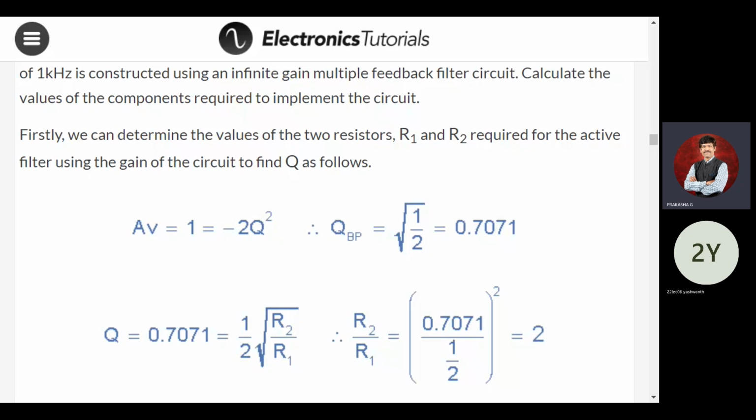One more thing, band rejection is also there. Band rejection, what is it? I'll give the same input signal to the low pass filter and also to the high pass filter. The low pass filter gives the low pass output, and the high pass filter gives the high pass output. Then I'm going to sum them, getting the summation of both: low pass plus high pass. In between, whatever is cut off will be retained as it is.